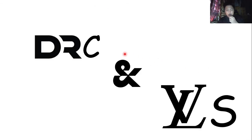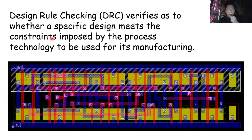I will now talk about DRC and LVS. First, what is DRC? DRC is design rule checking. It verifies whether a specific design meets the constraints imposed by the process technology to be used for its manufacturing. So in order for our design to be used for manufacturing, we need to verify it using DRC and LVS.